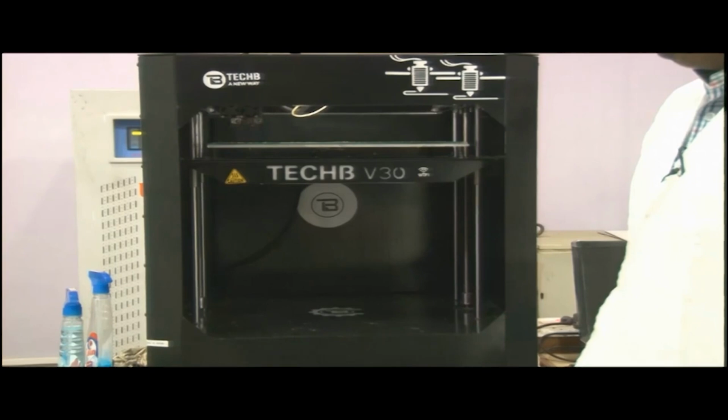FDM machines produce products with precision, but the precision level in SLA is higher. Higher resolution objects are more possible to produce in SLA because resin is there. The resolution is primarily determined by the optical spot size of either the laser or the projector, and that is really small in SLA. In FDM, it is the printer resolution, which is a factor of the nozzle size and the precision of the extruder movements. That extruder we will discuss in this demonstration as well.